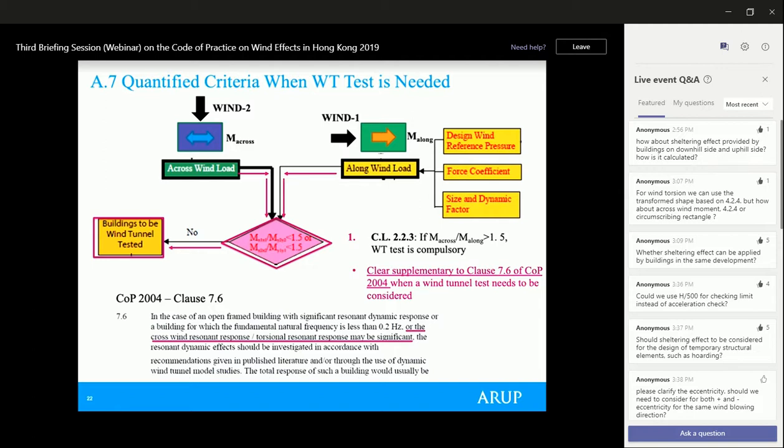Yeah, and also I think maybe Alexis can further supplement. So I think maybe the structural designer can first, from a conceptual design perspective, review why the first mode is torsion governed, right? Because normally we think it's lateral governed. So is there any way that the designer should further increase the torsional stiffness to mitigate that? I think this may be another way we can think about.